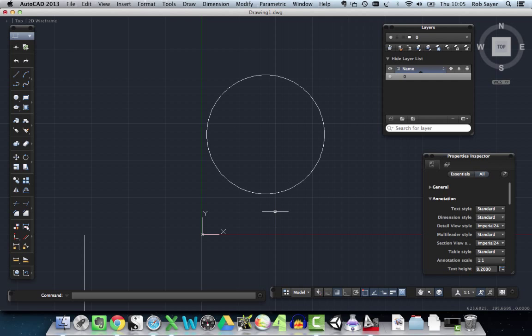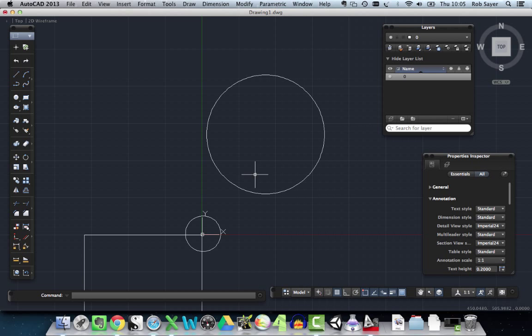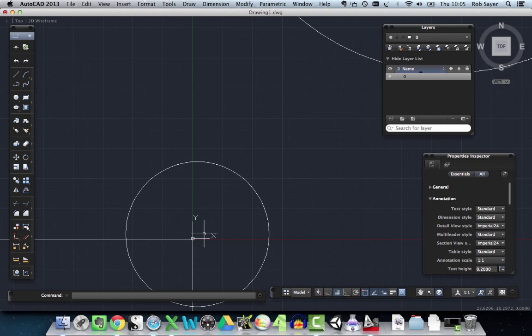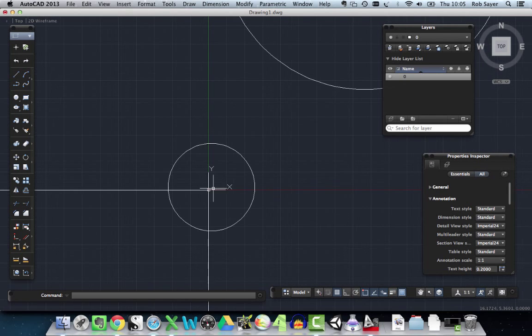The other thing to do is to have another go with the command line, and just, as you're on the screen, type out CIR, and you'll see circle comes up. Hit enter or space with your left hand if you like, and then it says specify center point for circle. Well, I'm going to make my center point 10 mil up and 10 mil across, because it's a silly place to be, just very slightly off that universal coordinate system. And then I can specify the radius, and my radius is going to be 150 mil. So basically it's given me a 150 millimeter radius circle slightly off center. You can't see that because I literally went up 10 mil from the 0, 0 point.